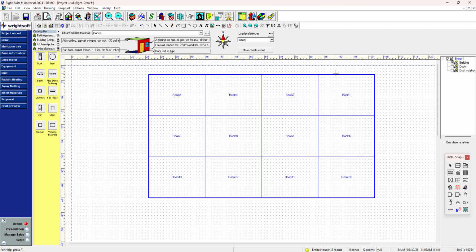If I were to start drawing windows here, that would change significantly. All right, so let's remember we had 25,000 BTUs for cooling. Now that I've put some windows, and windows are terrible from an insulation perspective, especially in the summertime. They allow in all that hot sunlight with all of that hot energy associated with the sunlight, all right? And of course, a window is going to have less insulation compared to a wall, right?